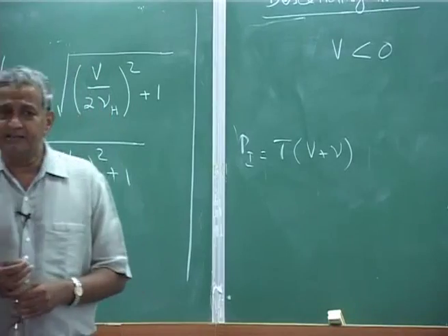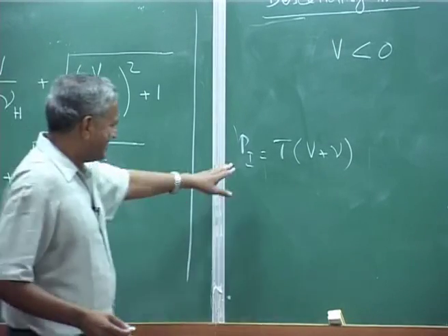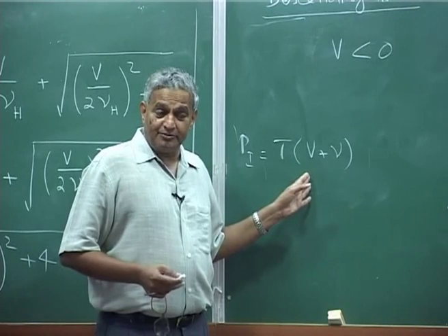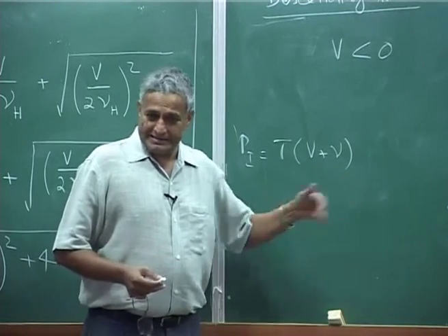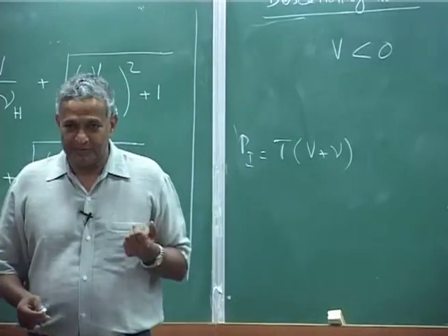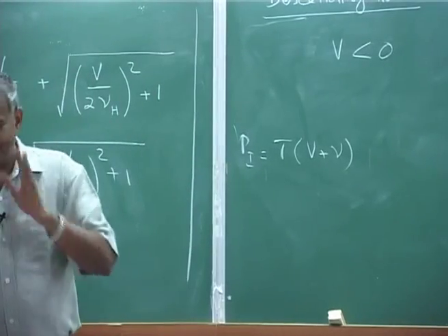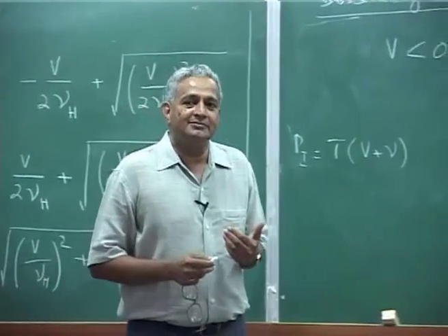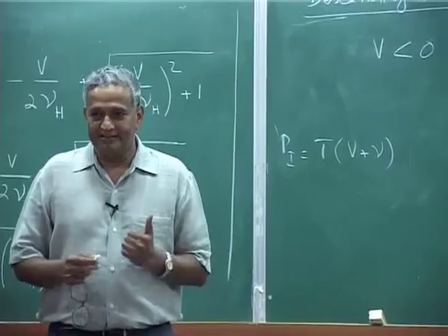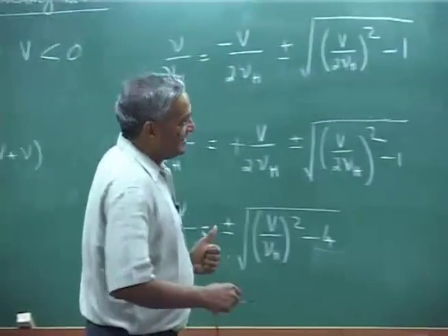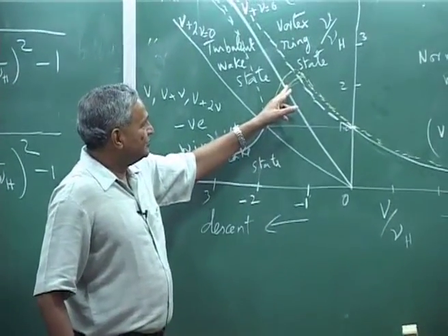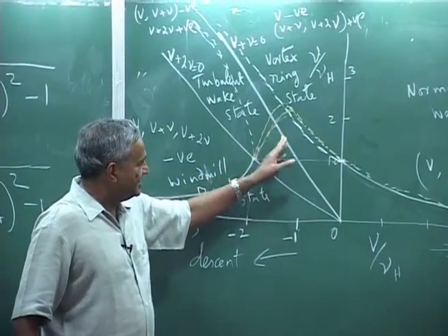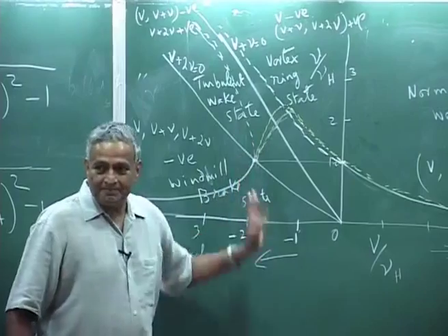This is called the auto rotation, but technically you do not take this particular velocity, because you have profile drag also, and then the tail may take some power, and the fuselage also may get a little additional drag. So, usually you design at a velocity slightly faster than this point, a little faster, you go a little this side.